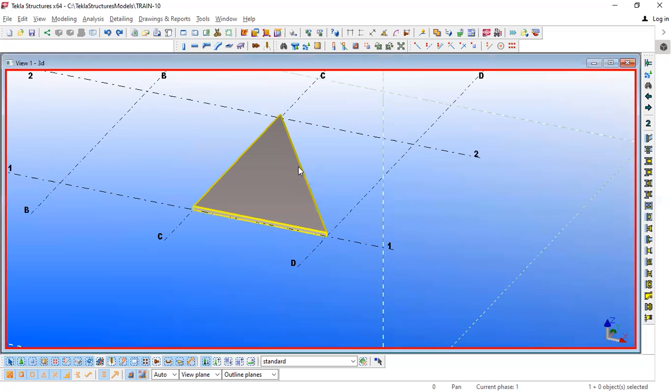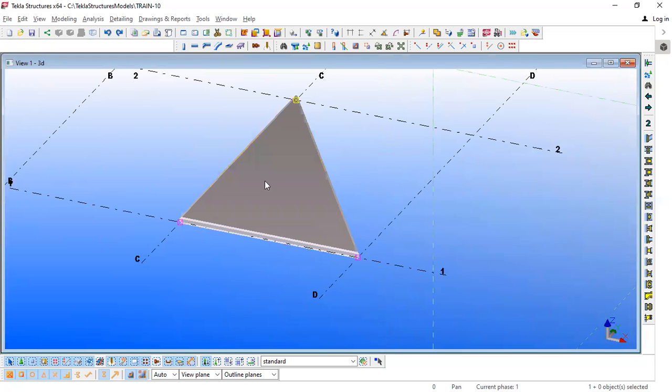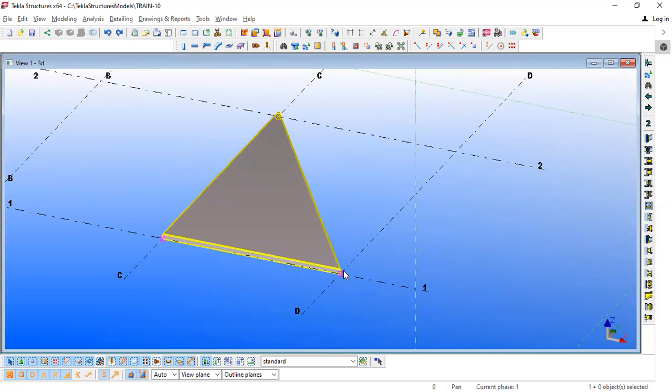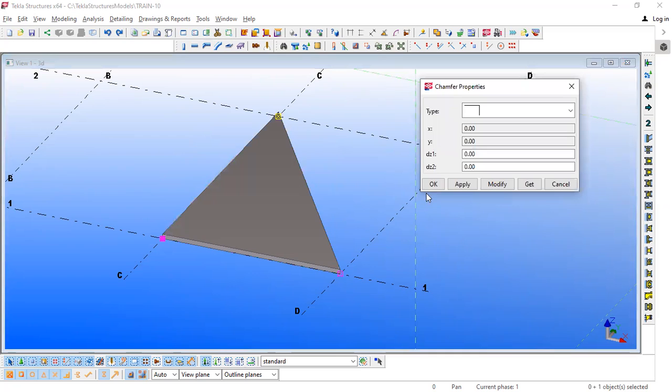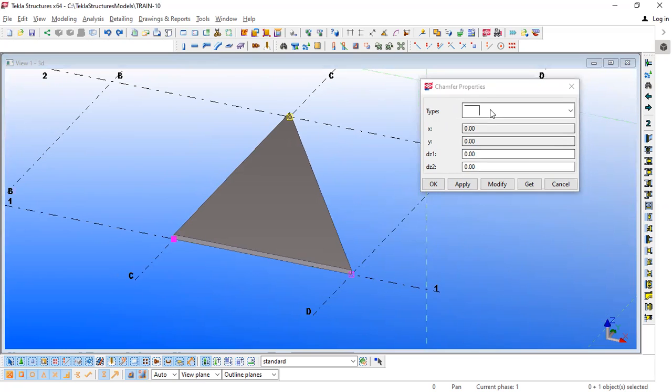Okay. Also, here we have properties like polygon, polybeam. Okay, so we'll just try out one option that we tried in the polybeam. So yes, we have a similar properties here for contour plate also, like polybeam. So we can modify this plate like a polybeam also. So I'll just say 1000, modify.